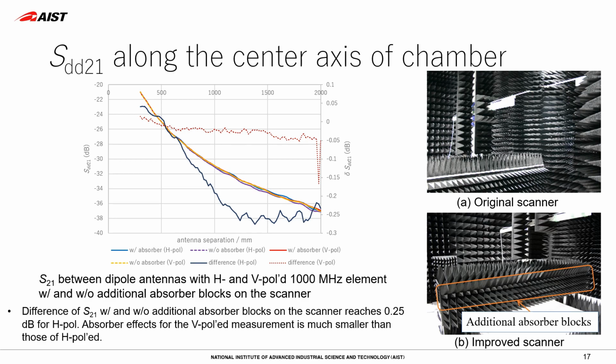This is one approach to implement it. To exclude the unbalance effect caused by the balun, the balanced-to-unbalanced transformer of the dipole antennas, a mixed-mode antenna measurement was carried out. Thus, taking SDD21 is identical to the site attenuation, although the value is almost doubled.